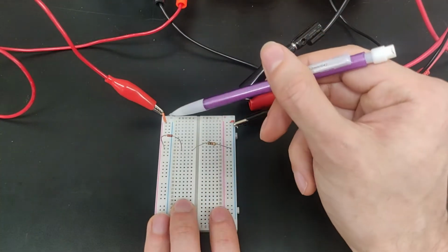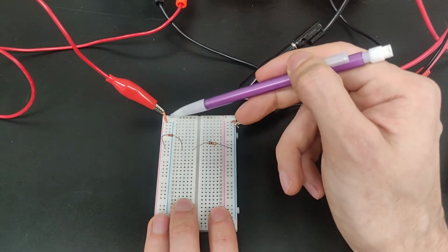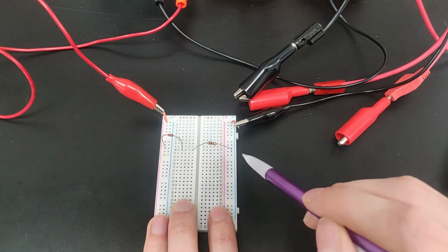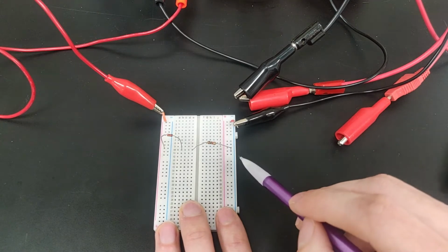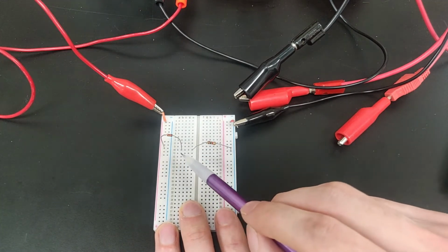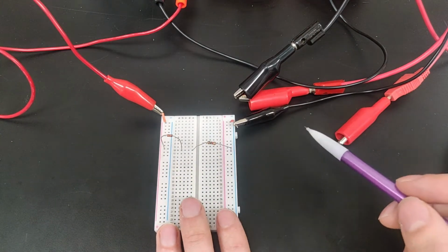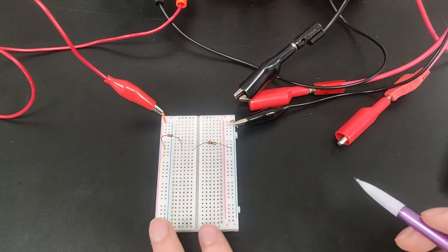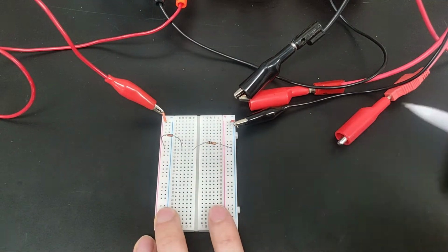So right now I have the forward bias circuit built, and just to trace through the circuit, we have current coming in from this positive lead, going through our forward biased diode, going through our 1000 ohm resistor, and then going to ground. So the reason why we need this resistor in series is that eventually, once we reach a threshold voltage, current is going to freely flow through the diode, and so if the resistor was not there, it would short circuit once we reach that point, and we don't want that to happen. Also, we're going to need this resistor to find the current going through our diode.